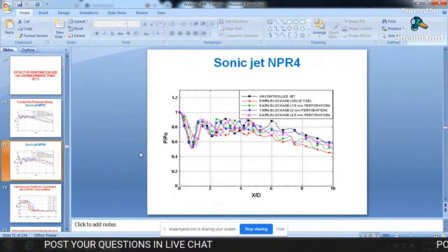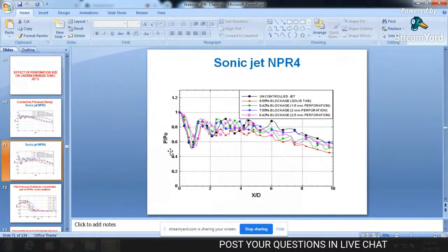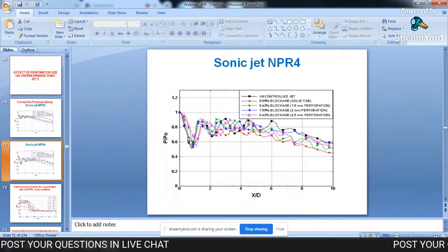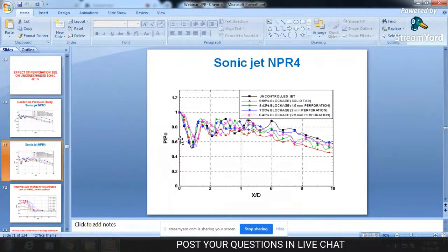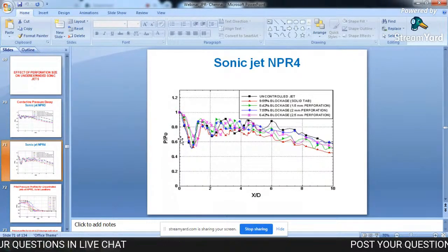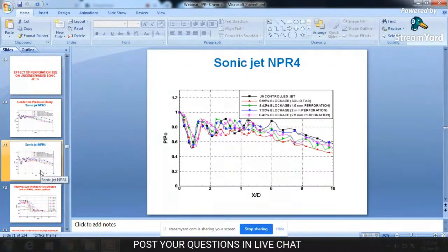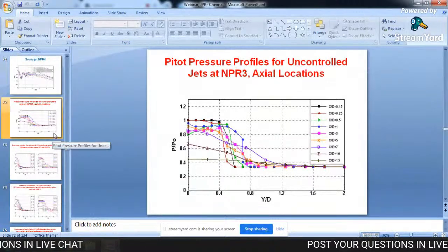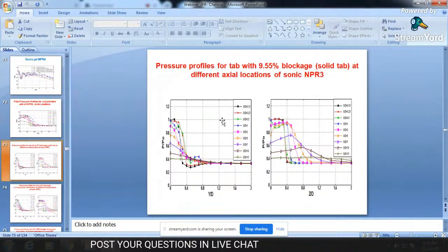So we retain the pressure as sensed by the probe; we cannot convert it into Mach number, because shocks are there, losses are there. That derivation is for isentropic flow, and here the flow is no longer isentropic. Now the same thing was continued for the y direction, and now we have the y direction and z direction.